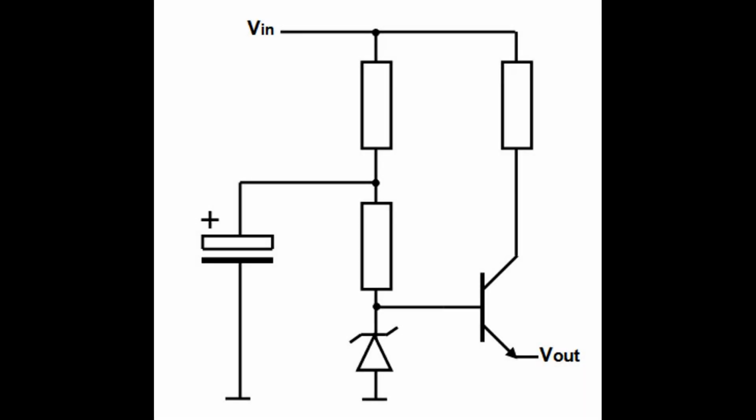Now take a look at this transistor driving circuit. Can you recognise the low-pass filter? Without even needing to write a single formula or understand the complete function of this circuit, we can understand that for some reason the designer has used a low-pass filter to block high frequencies from the input.